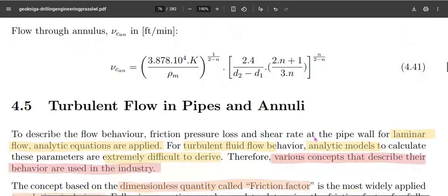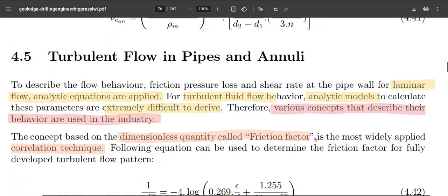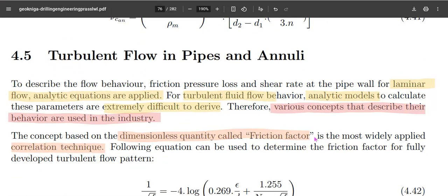So, considering the turbulent flow, as mentioned in the last video, there is a critical Reynolds number, usually around 4000, where we end up in a fully turbulent flow, for which we cannot utilize similar equations to those we introduced earlier for laminar flow, where we had a closed-form solution by simplifying the equation, the physics, and the geometry to compute the pressure loss. We can still do it, but it won't give you the proper value.